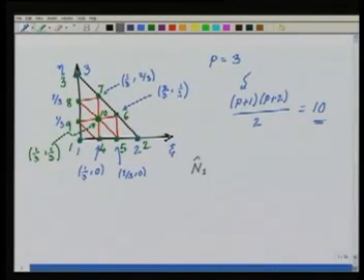So let's say that I would like to define N1 as a function of psi and eta. This function N1 is with respect to this node, such that N1 is 1 at the node with coordinates 0, 0 and 0 at all other nodes. So how can N1 be a cubic polynomial in terms of psi and eta and vanish at all other nodes barring my node 1?